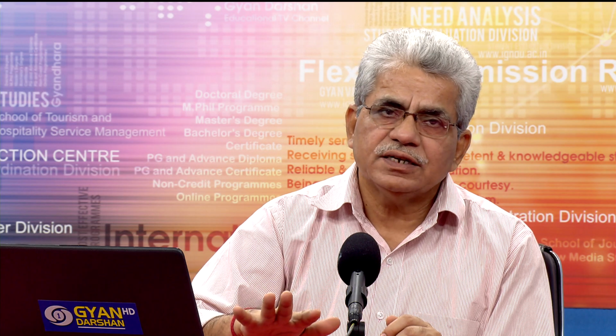So where we are doing our excavation, we must know whether any utility, any water pipeline, sewer pipeline, any communication cables or electricity cables are there. If they are there, we have to take proper care while doing the excavation.